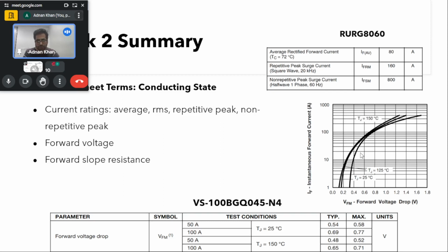You can cross check with these what is given in the table with this device, and it will follow exactly that thing. And for that, if you can see, at higher temperature, like at 150 degrees centigrade and similar currents, you can see that the on-state voltage drop decreases. Like we have 0.48 now for 150 degrees centigrade.